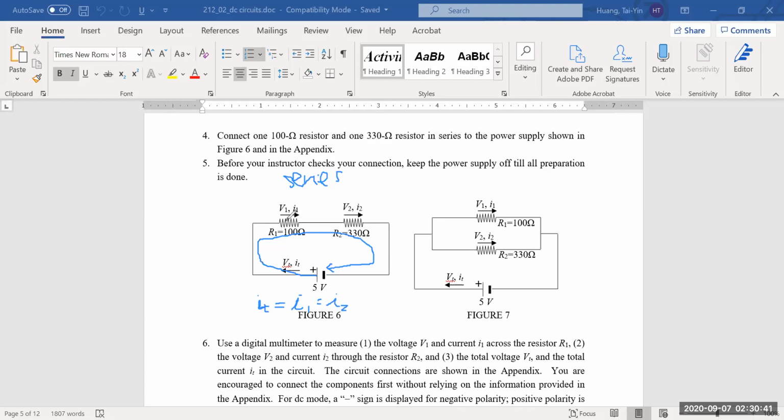And how do we calculate the voltage? You're going to measure it, and then you're going to find the theoretical value for that. To measure voltage, you basically just have a voltmeter connected across the component, and then you can measure the voltage. To calculate each voltage, first of all, you need to calculate the total current first. Then, V equals IR is the equation that you're going to use. Okay, V equals IR.